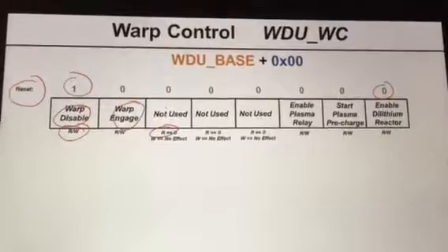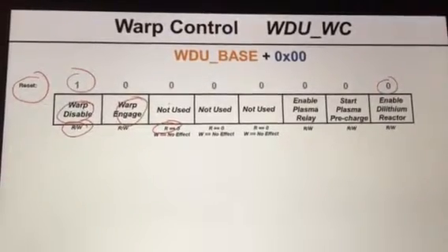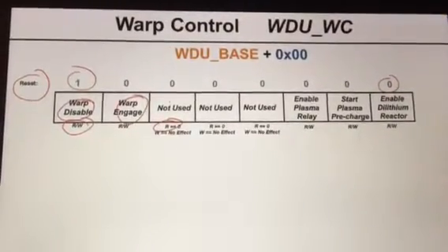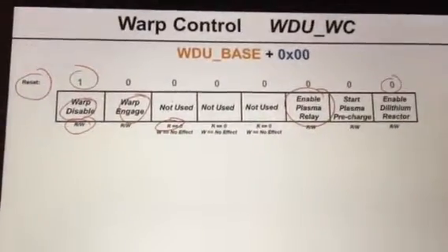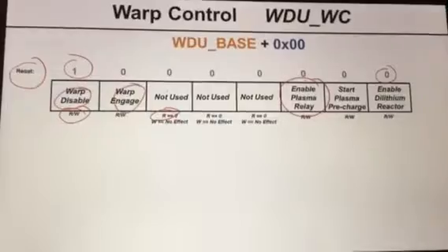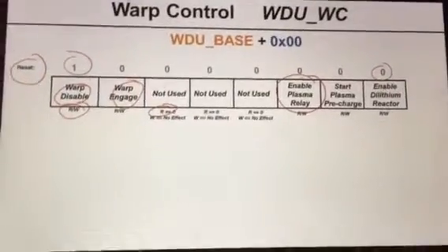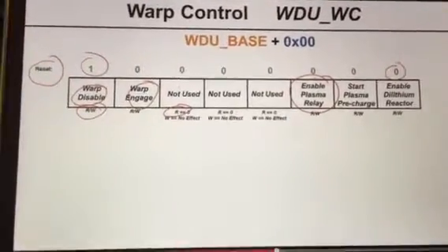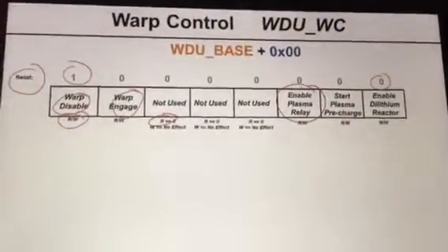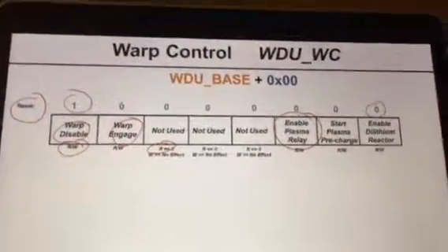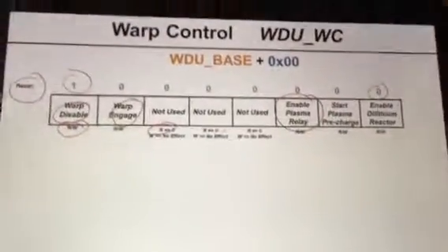And so you just look through these registers and you can get a good idea of what it does. What I like to do on any new peripheral is just look at the register set and how it's documented. You can get a good idea of how it works just by looking at the registers. Now, there's not really any state information of how things are sequenced, but you can get a good idea of what's going to go on.